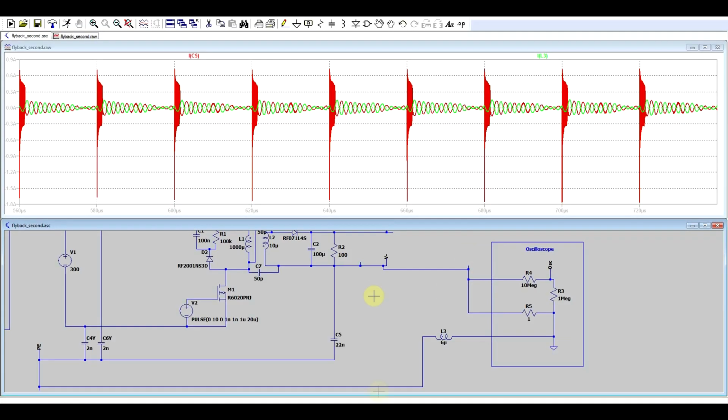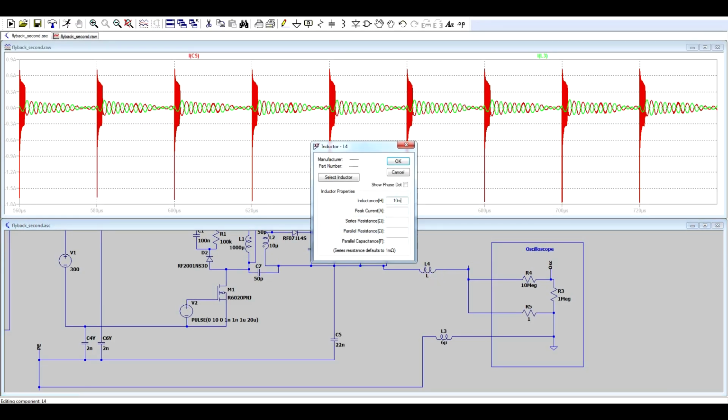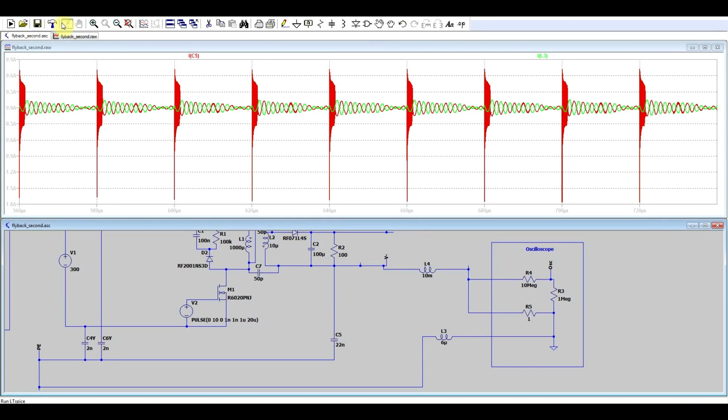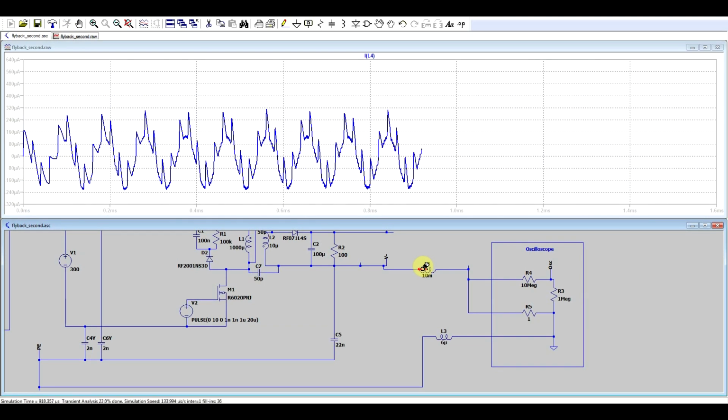Now, there's two ways to keep the noise inside the supply regardless. Either increase the impedance of this external connection. This is where disconnecting the protected earth helps, since this way the noise can no longer be coupled through the external circuit, but we're not allowed to disconnect the protected earth since that's not safe. We can add a very big inductance on the line. So let's say if I add 10 millihenry, then the noise coupling through it will be negligible, so microamps.